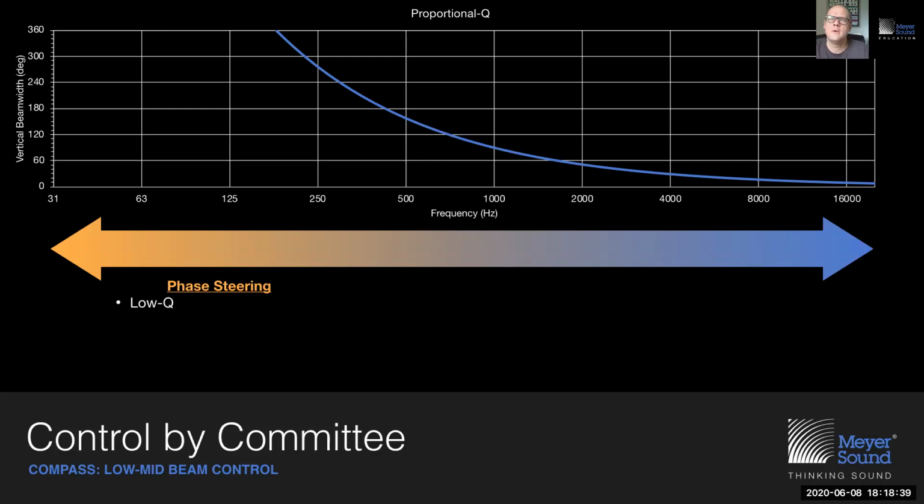They're low Q. And that means that even if you have an array of 12 to 14 or 16 loudspeakers, at low frequencies, all audience members live in the shared custody of all these low frequency transducers. If they're omnidirectional, they cannot steer clear from each other's territory. So at low frequencies, we're in the joint custody of all these omnidirectional elements in that frequency range, mind you.